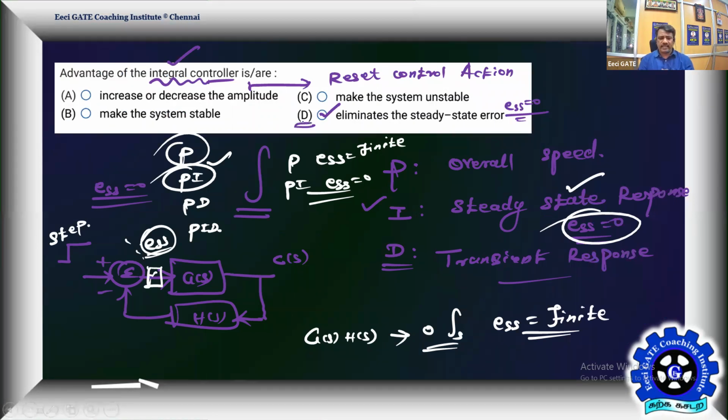It eliminates steady state error. By adding integral action, the stability of the system is always decreased a little. That means it does not improve; it is going to make the transient performance a little worse, because the stability is decreased. You can think of it as friction being decreased. That's a drawback of integral action. Integral action will degrade the transient performance. It will make oscillations a little more in the system, but still it is going to eliminate your error.